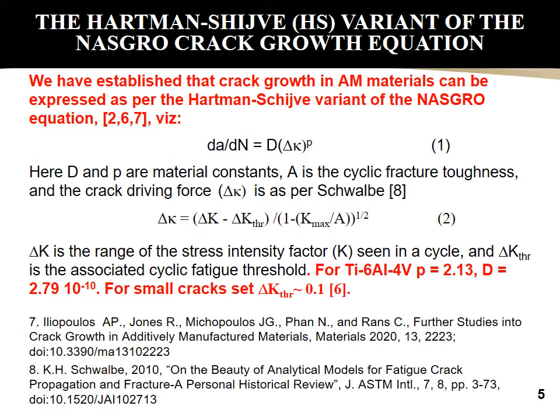In this context, we have established that crack growth in AM materials can be expressed as per equations 1 and 2. In equation 2, the crack driving force delta kappa is as first defined by Professor Schwalbe. For Ti-6Al-4V, the constants are given in the slide. In order to get the small crack growth equation from equation 2, you merely set the threshold value to be small.